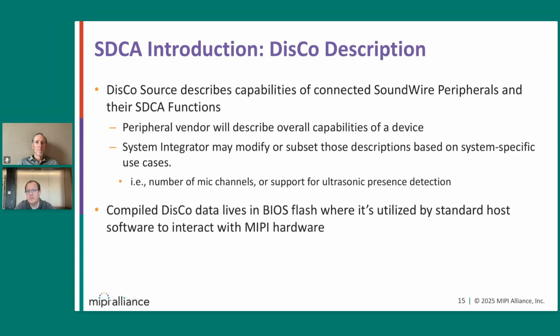Those descriptions can then be modified by a system integrator, maybe because they're combining peripherals in a novel way, or maybe because they want to be more specific about the device capabilities or host software behaviors, and customize it for their particular system. Once those customizations are done, the ACPI source language is compiled and lives in the BIOS flash, where host software can find it.